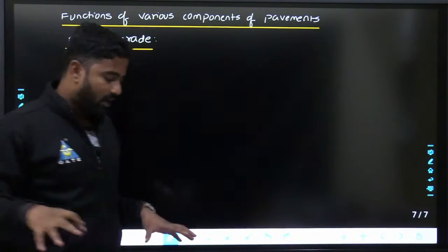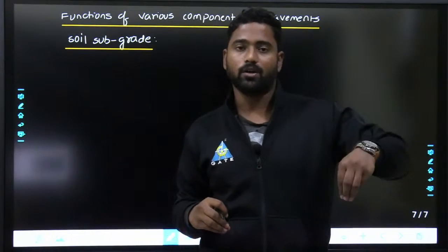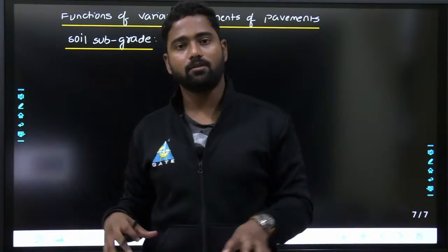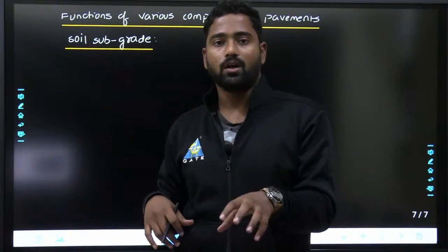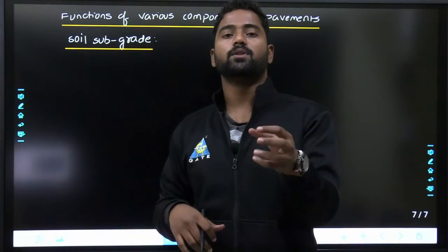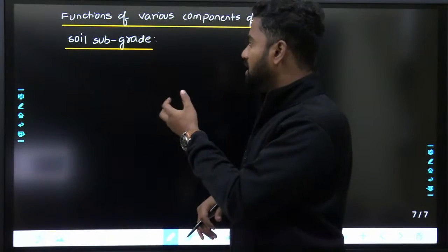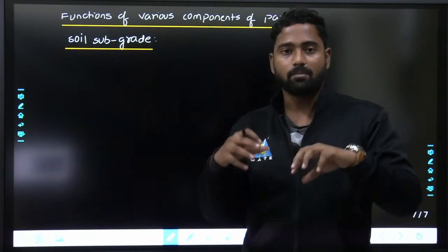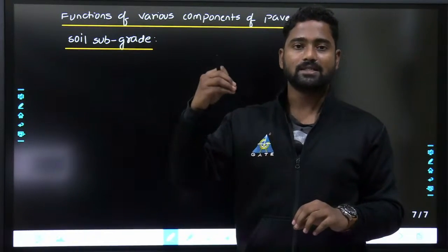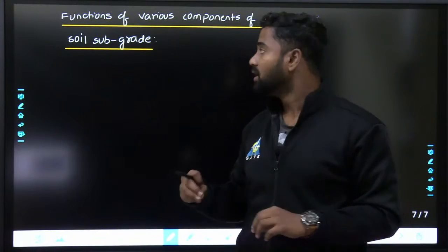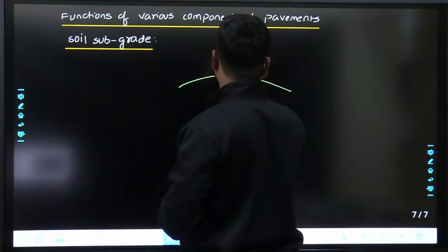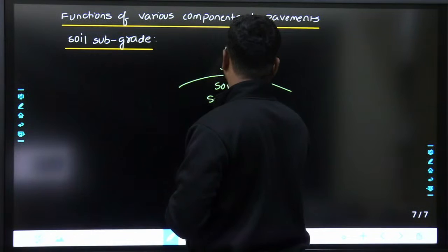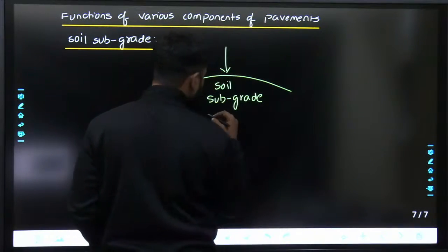The soil, finally the load will be taken by the soil only, right? Whatever the load that is by vehicles and all those things, finally the load will be taken by the soil only. So the stresses in the soil should be within the permissible limits. Generally you might be designing in your RCC and geotechnical engineering what should be the bearing capacity of the soil, and stresses developed should be less than the bearing capacity of the soil, right? So whatever the load, finally the load will be taken by the soil subgrade only, and stress should be within permissible limits.